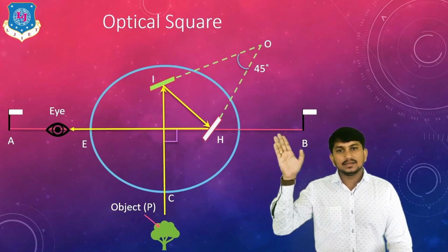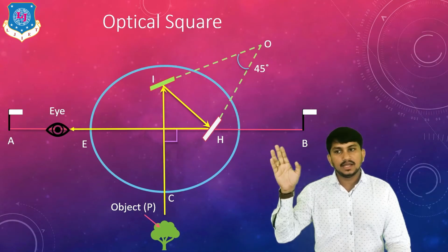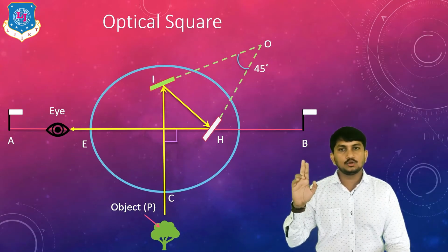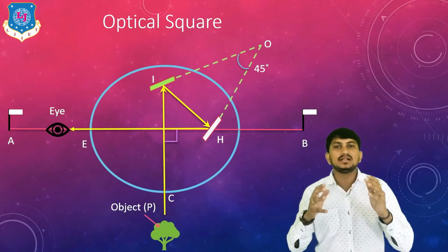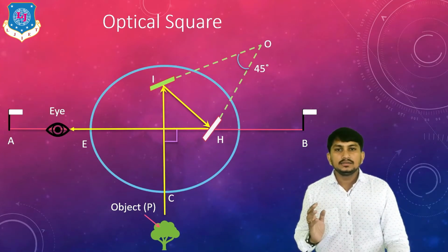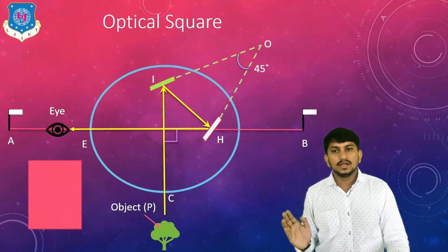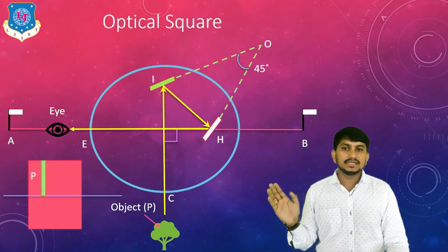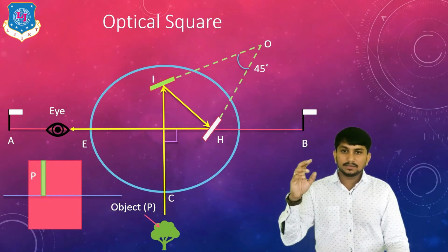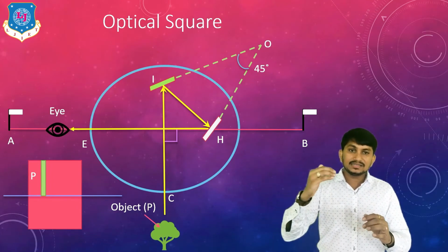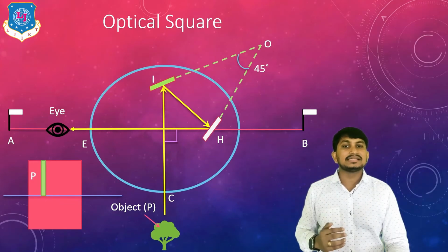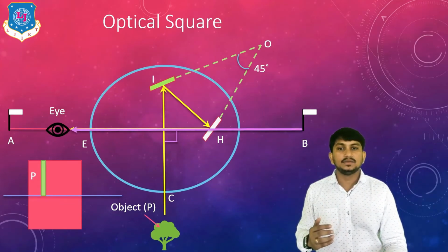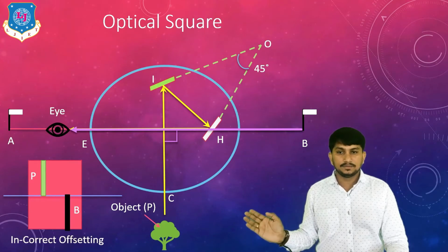Here I is the actual mirror and H is in 2 parts. The above part is the mirror and the below part is simple glass. So the reflection of the light is from P. At the above part we can see the object P. At the below part, because of the simple glass, we can clearly see the opposite end, which is station B and its ranging rod. So at the bottom part, we can see the ranging rod at B.